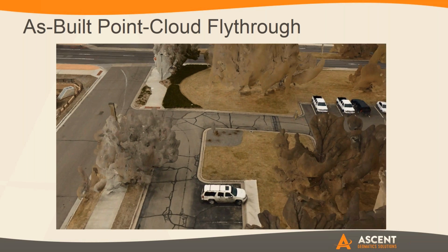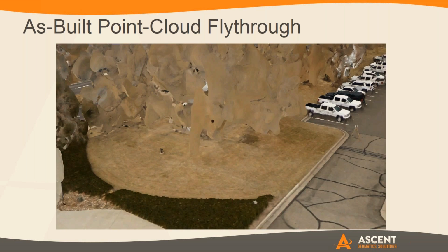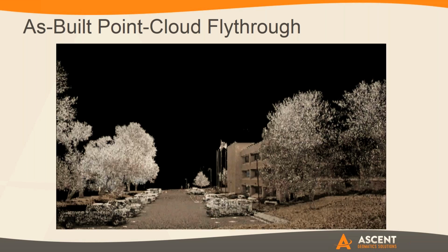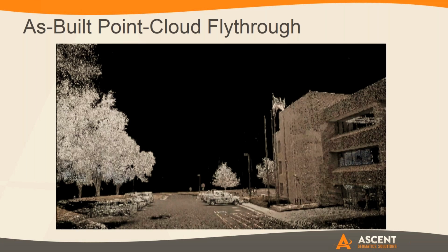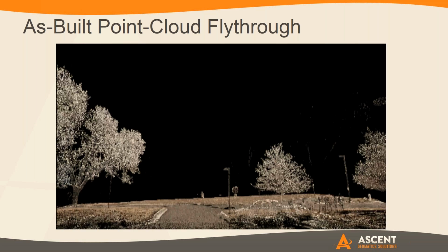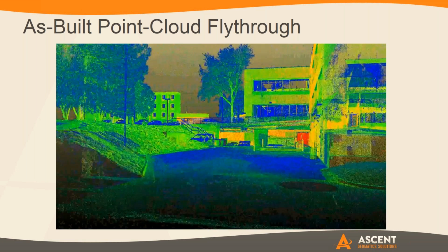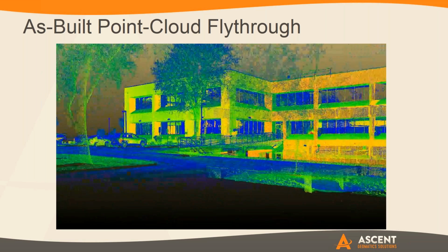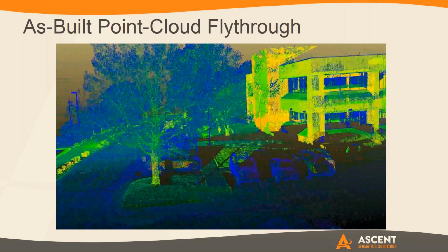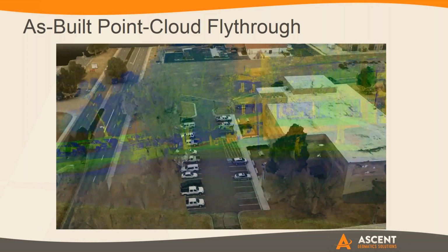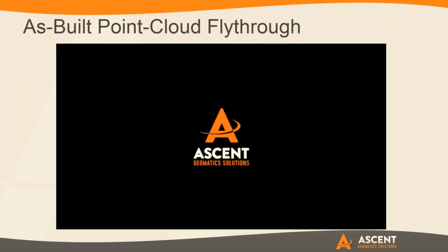And in a second here, you'll actually see it turn into a LiDAR point cloud, which is where you start to get the true detail of what the curb and gutter look like, literally the design survey that you need to get that project accomplished. So it's using a couple different tools to get a much greater perspective on how to plan this out better and get better detail, and again, for a very reasonable cost compared to a guy going out and hand topoing an entire parking lot, where you're never going to get all those subtle undulations that you would from this type of data set.